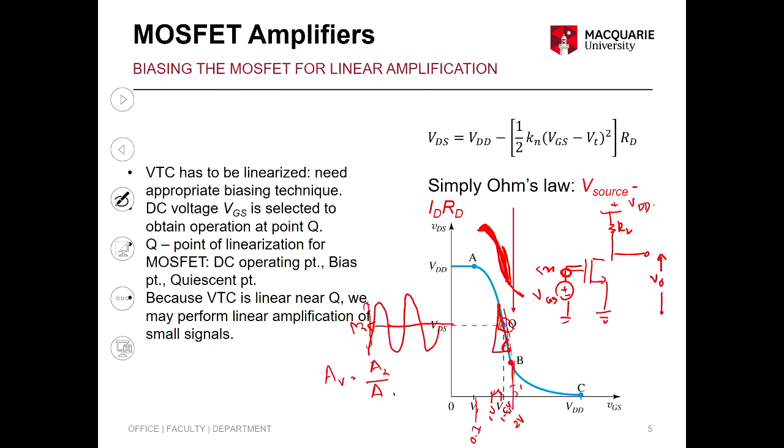In your circuit, I'm talking about your design, depending on what point you bias, you will notice you can have different gains. So if you want to increase the gain, you can increase your VGS in your circuit, right? Our spec for assessment 2, I think, is 28 dB gain. So let's say you bias it at 0.8 volt or 0.5 volt. I think the threshold for these circuits is 0.3. If at 0.5 volt you don't get the right gain, one thing you can do is bias at a higher voltage, right? So you bump up your gain.